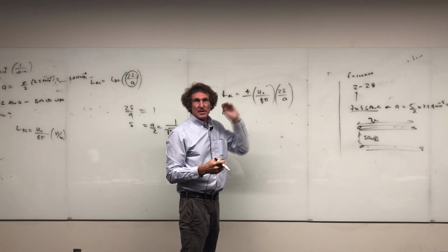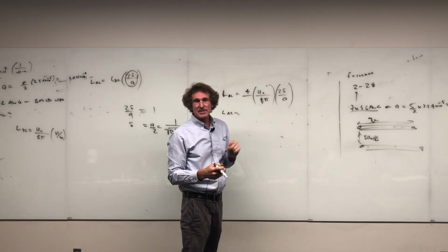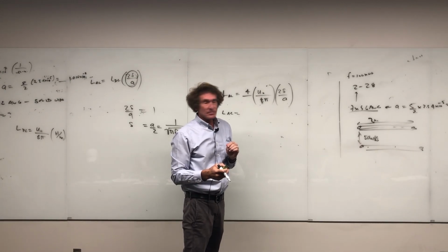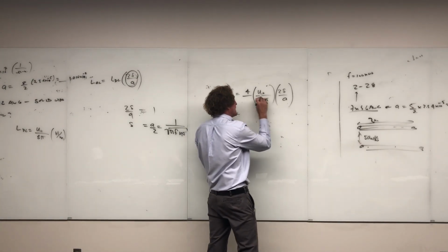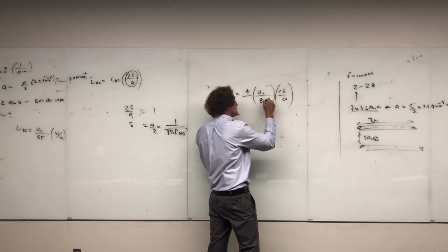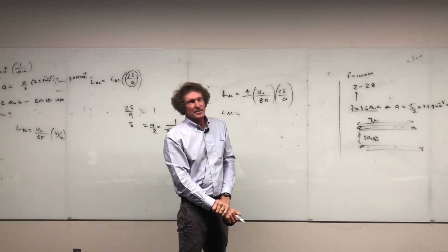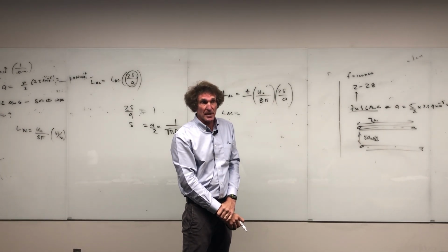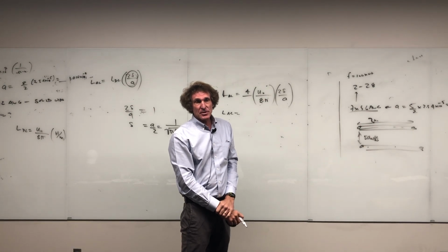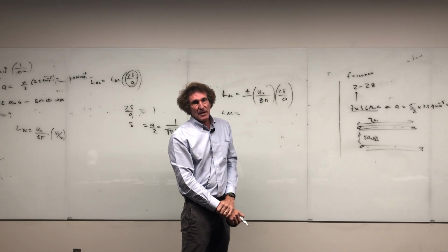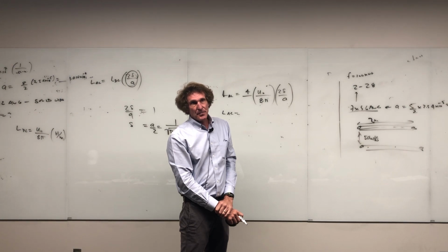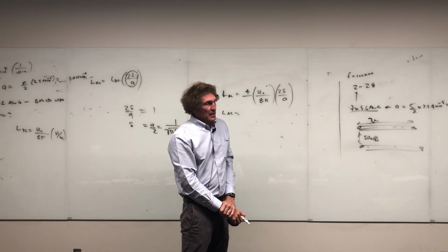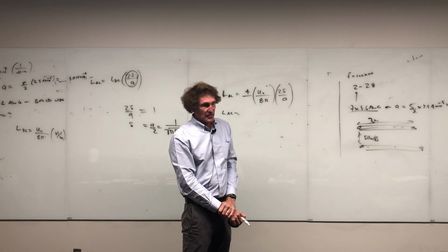I'm trying to do this methodically, but I want to cover a little something, and we've only got 10 minutes left. What is that symbol on the bottom for the pi? This is 8 pi. The DC inductance is just mu0 over 8 pi, that's henries per meter. Please, I'm trying to make sure that you're clear on this stuff because it's important. Engineers are oftentimes careless right at this point, and they make some colossal mistakes. Well, you'll find this out the hard way usually.